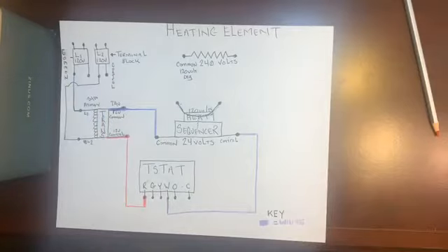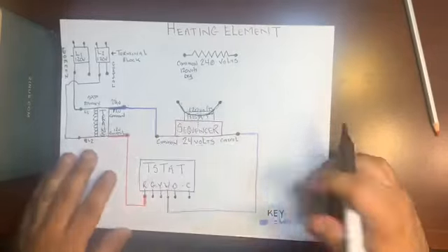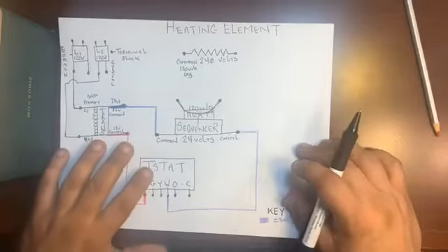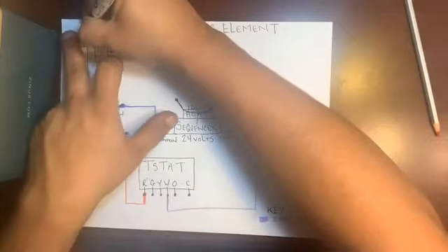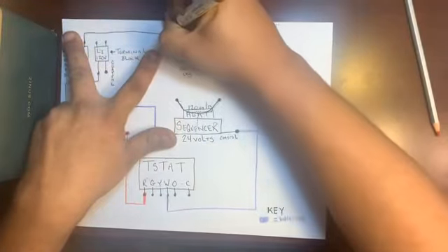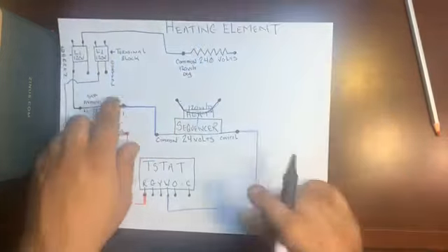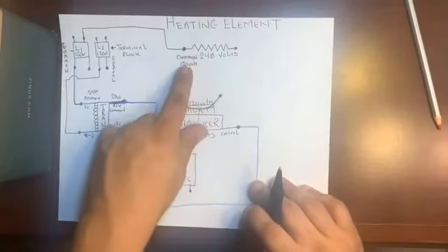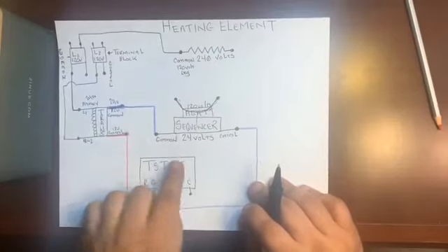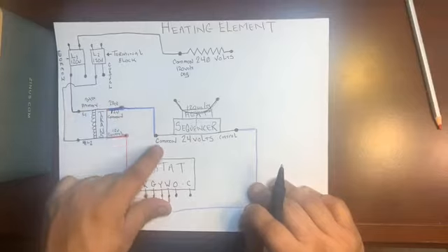Let's go ahead and get that drawn in so we get a better understanding. We're not going to use blue and red because that's for the low voltage. We're going to go ahead and use our pen. So common to L1 and common here. So I'm going to come up and I'm going to bring 120 volts to this heating element at all times. There's 120 volts. Now this heating element has a common 120 volts. Just like Mr. Heat Sequencer says, don't play with my common. You give me my common, Mr. Transformer, every time I want it.